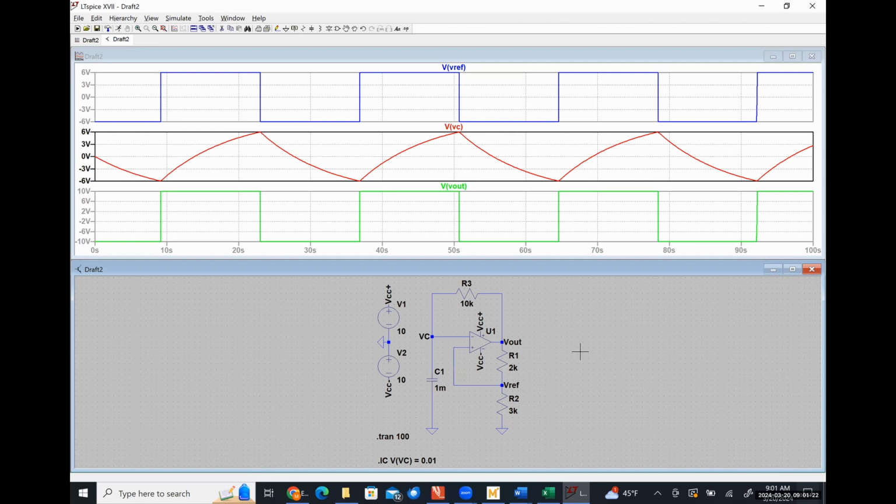It's similar in as much as you have that dead band where it doesn't transition. So you didn't do a circuit like this, but the output is effectively the exact same thing. Yes. So the Schmitt triggers and all that kind of stuff are used for HVAC control and all that kind of stuff to make sure that you don't short cycle the compressors and all that kind of jazz by having it constantly go off and on. So similar application even for temperature control.